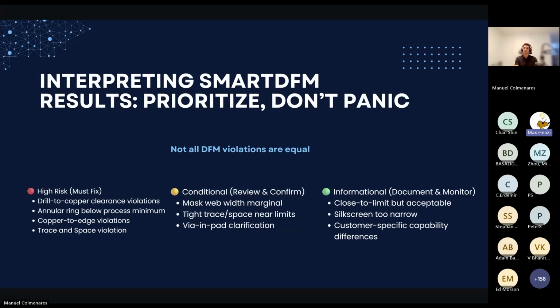If I have a 10 mil clearance between my polygon and adjacent features, sometimes if it's a 10.01 gap, it doesn't pour through there. Now I have an open in that polygon. Okay, it's probably not the end of the world, but it may be if you're relying on that poured through copper plane to make a connection to a via, for example.